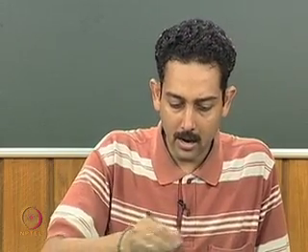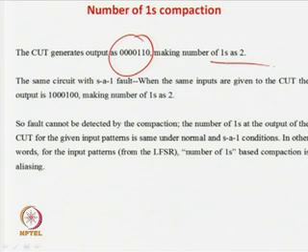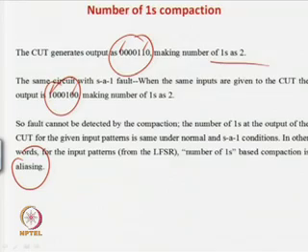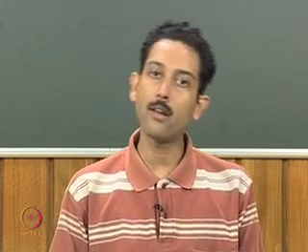So, this is the output when the number of 1s is 2 and the circuit is normal. Now, this is being generated when the circuit is faulty. You can see that there is a difference in these 2 points, but in both cases the number of 1s is 2. So, this kind of compaction cannot determine that stuck at fault. That is actually called aliasing; for the stuck at 1 fault, LFSR aliasing has happened. Okay. So, now if aliasing has happened, your fault coverage has decreased.